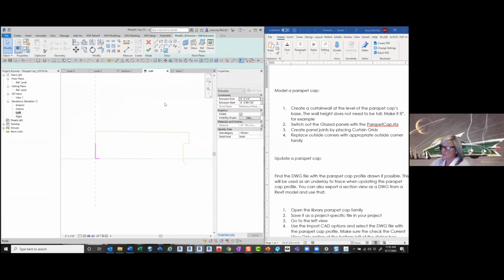I'll just do pick lines, and then I'm going to hover over this and I'm going to tab. I'm going to keep tabbing to get as much stuff as I can. Once I see what it's going to give me, I'll pick. And it already picked all of those lines for me. You don't need to constrain. Don't worry about all these little padlocks. The less constraining you do, the better. I feel like there's potential to over constrain stuff, and it can really bite you later on. So don't worry, you can just ignore those.